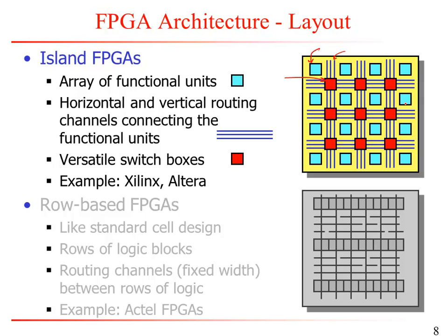And if you look at the basic structure of FPGAs in the past 20, 30 years, this has been the backbone of FPGAs, but over the years, people have added more bells and whistles. They've added more specialized features like fast carry paths for efficient implementation of adders. They've added multipliers, RAM units, and stuff like that.